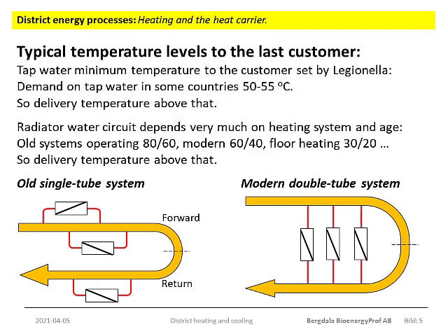And we start by determining approximately the temperature span we will be working in. The starting point must be set by the end user. The end user will want to use the hot water delivered in a heat exchanger to produce hot tap water and to produce comfort heating. As for tap water, many, if not most, countries have a legislation stating how the monitoring of Legionella bacteria shall be done. In some countries this has been specified as a lower temperature limit.